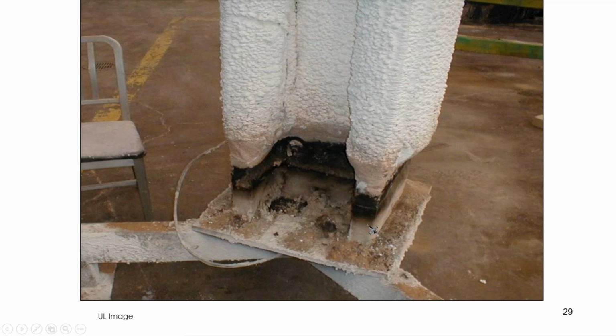And as such, then the steel underneath it, likewise, is very cool. So as we move up in elevation, the column comes out of that bed of sand and sees a reasonable amount of heat. So this lower section of the column would represent a heat sink, would lower the temperature immediately above it on the steel. So we need to maintain sufficient separation from the base of that column to the first level of thermocouples so we eliminate that edge effect.